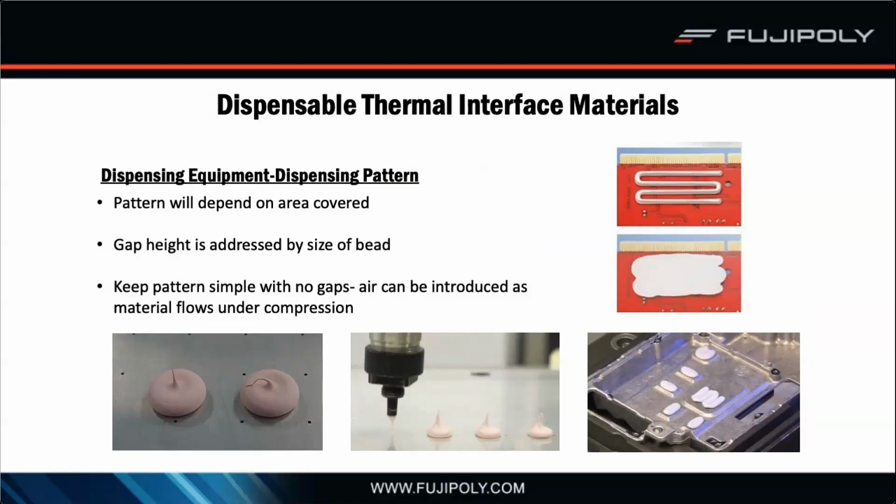Finally, when talking about dispensing these materials, you'll want to evaluate the best dispensing pattern for your application. Patterns will often depend on the area that you need to cover, as well as the gap you intend to fill. There's no real specific pattern that's going to work best. There's just some things that you want to keep in mind, such as keeping the pattern simple. Any pattern that introduces air into the TIM will impact the thermal resistance. If it's small, it could be negligible, but in other cases, it could be a more dramatic impact. The picture on the top right is a pattern that we wouldn't recommend, since as the material flows, there's going to be a risk of trapping air in between itself.